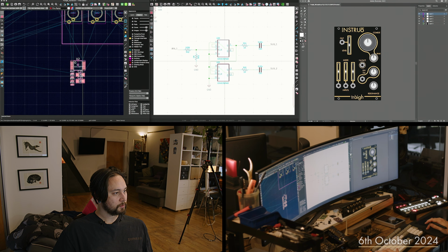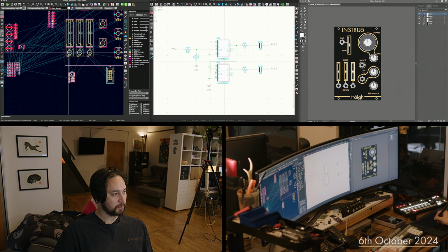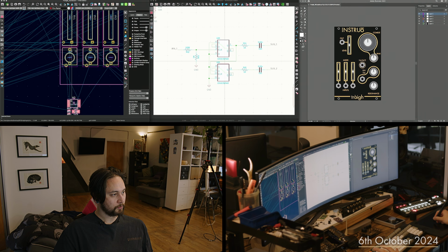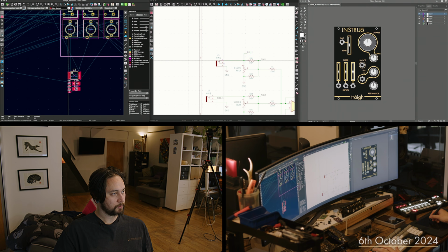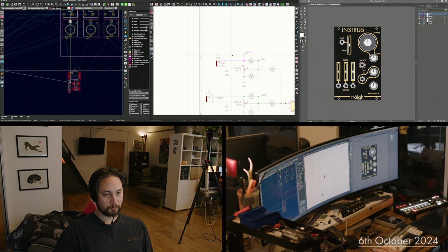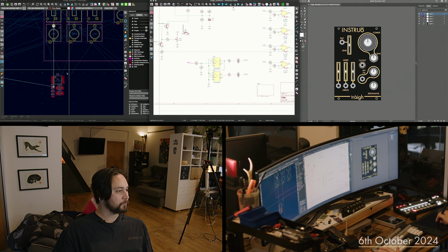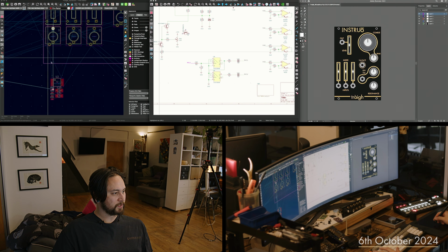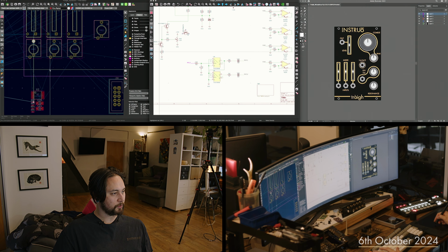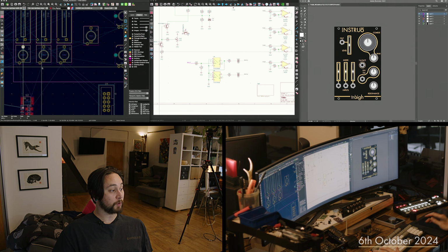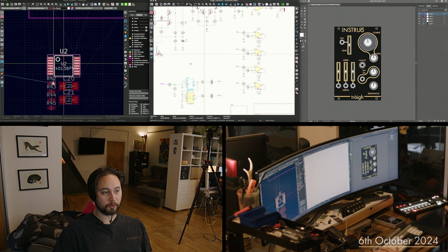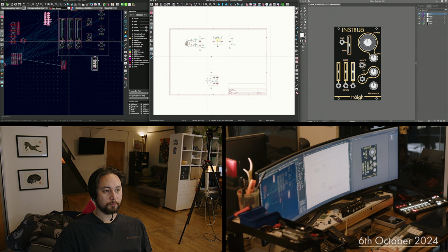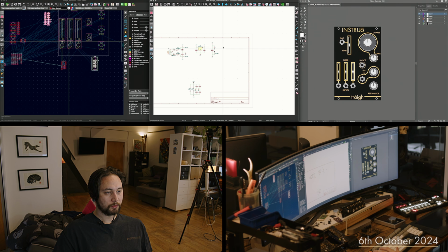that's them. So that's going to be intercepting the input signal from this jack, like that. That's going there, branching off there. So I can do that as a quite condensed cluster down here, and it's regulated itself, so it's got its own 5-volt regulator, so I can pull that in as well.